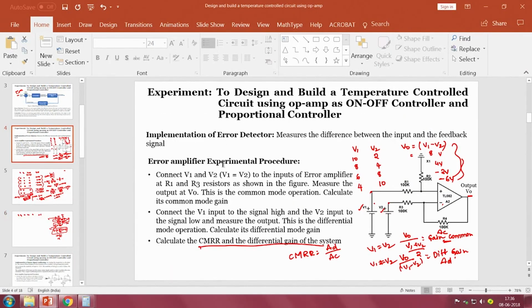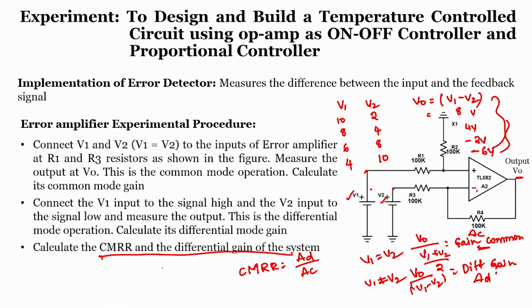Now we will see what is our actual thing, right. So, we have calculated and theoretically we got the gain of 1. So, theoretically as well as practically we got gain as 1 and CMRR as 58.4 dB. So, no problem with this differential amplifier for us. So, we can go ahead with this instrumentation differential amplifier too.